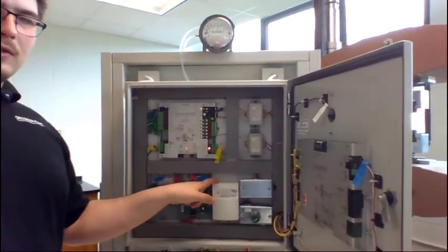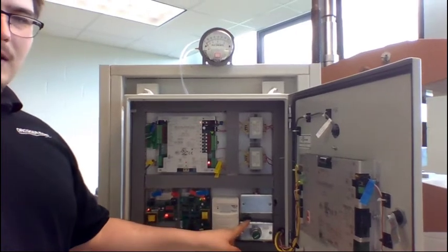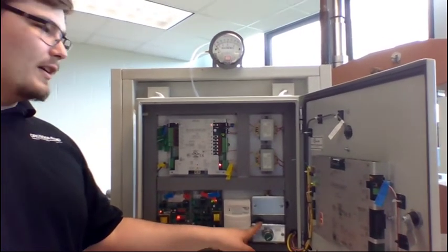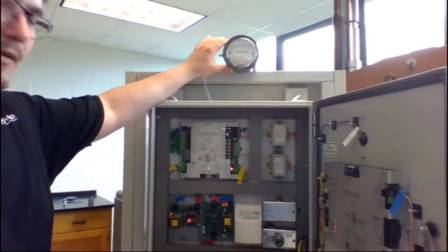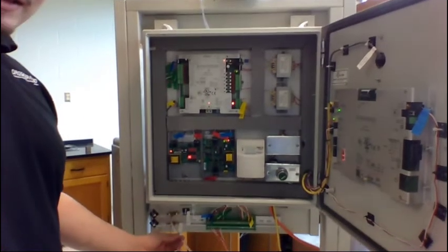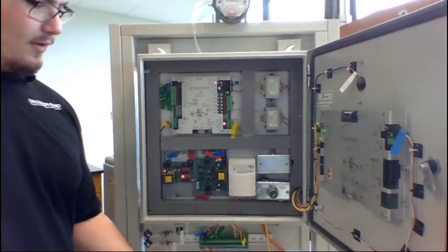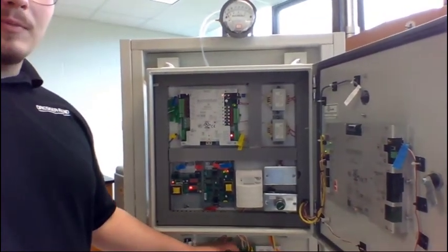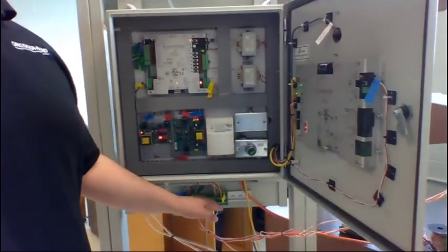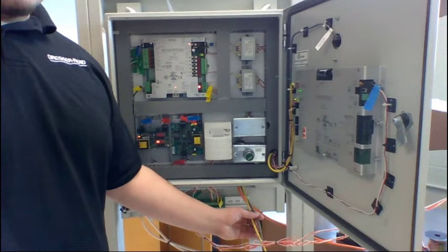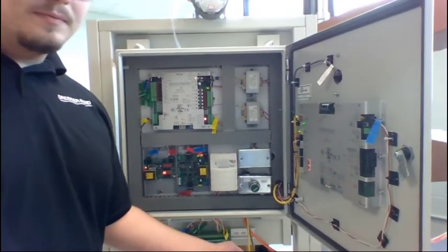This is a digital pressure transducer, differential pressure transducer, actually. Here's emergency on-off for the controls, for safety. Here's an analog differential pressure sensor. Here is the pneumatics that come all the way to the pitot tube, which we'll show in a second. Connector block, which connects down from the PLC, where the bottom then connects into the sensors. And then from here is an electrical line for the gray, and this one here is an Ethernet cable.